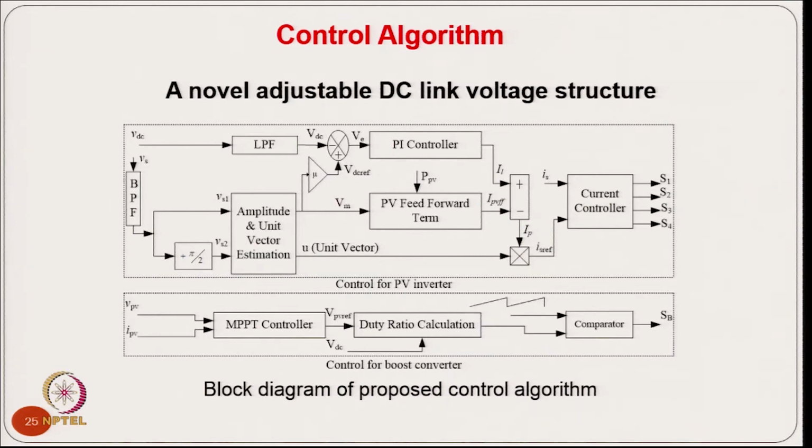So, what is shown here is another, this is the DC link voltage control where you have a reference. Typically in a country like India we have voltage fluctuating on the grid, but if the DC link voltage we decide in relation to the peak voltage of the grid, which we are getting from the sensed AC voltage, then the losses in the inverter can be reduced.